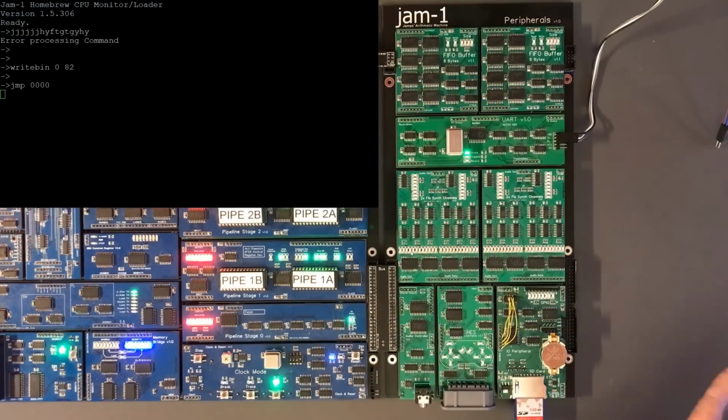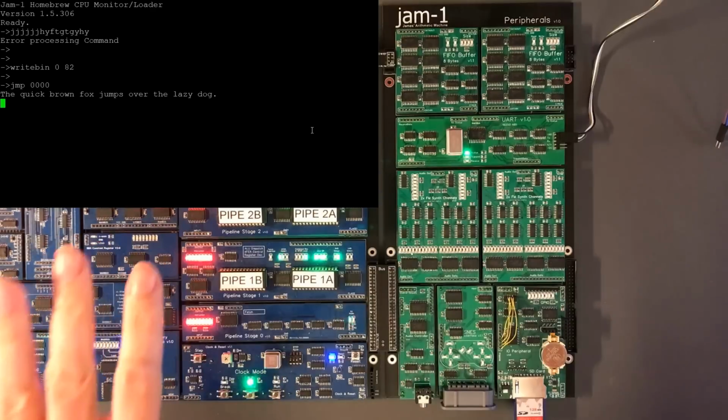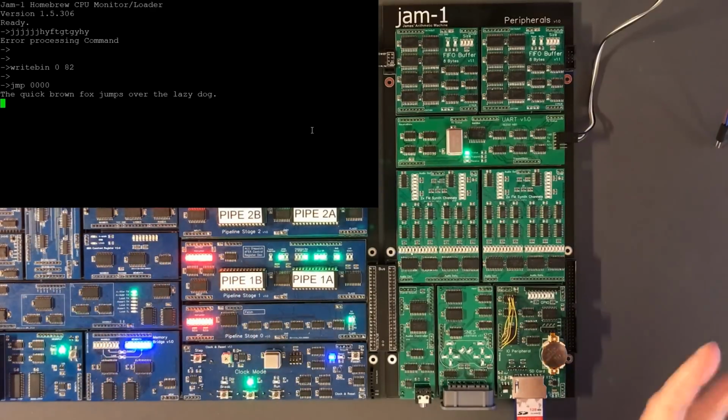It's actually quite difficult to outpace the UART just by typing on the keyboard. So I'm going to solve this by pasting some text into the window. Now this is with the CPU running at full speed. Here the test string has come out absolutely fine. But instead I'm going to switch the CPU down to trace mode, which drops the clock rate right down. And I'm going to paste it in and we'll see what happens.